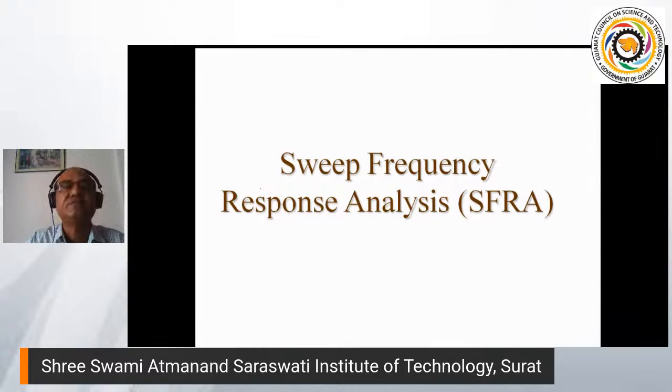Now we'll go for the next part, that is the sweep frequency response analysis. Sweep frequency response analysis is normally done for a transformer.